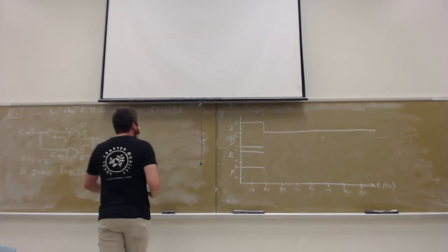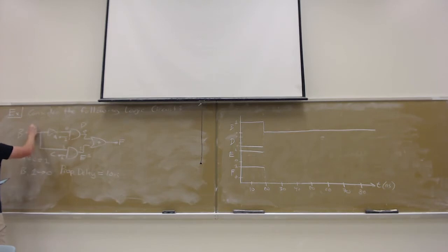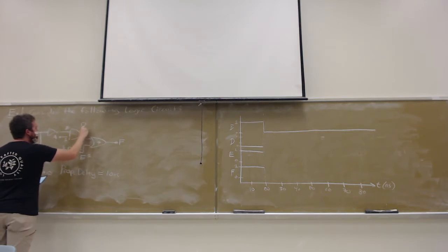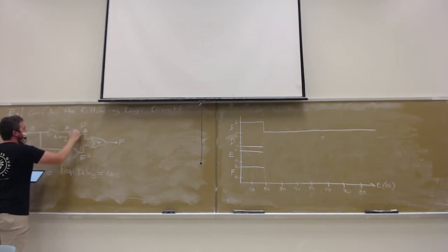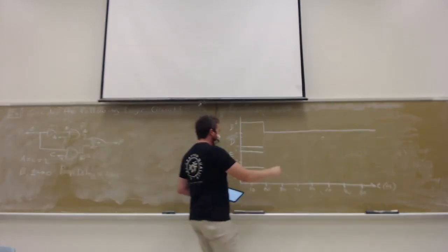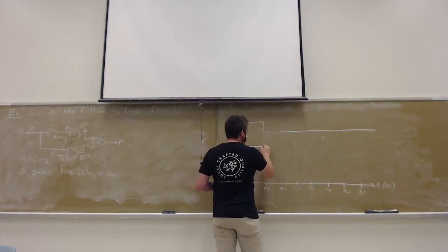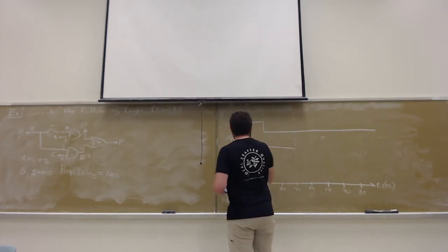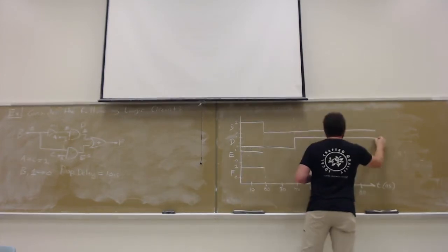Now the switch from B equals 1 to B equals 0 affected D. B goes to 0, which means we have 1 and 1, which means the output D is 1, but it doesn't occur until after 20 nanoseconds, right? We pay 10 nanoseconds for the inverter and another 10 nanoseconds for the AND gate, which means it's another 20 nanoseconds, from 20 to 40, before D catches up and clicks over to 1. So it goes from 0 to 1 and then hangs out.